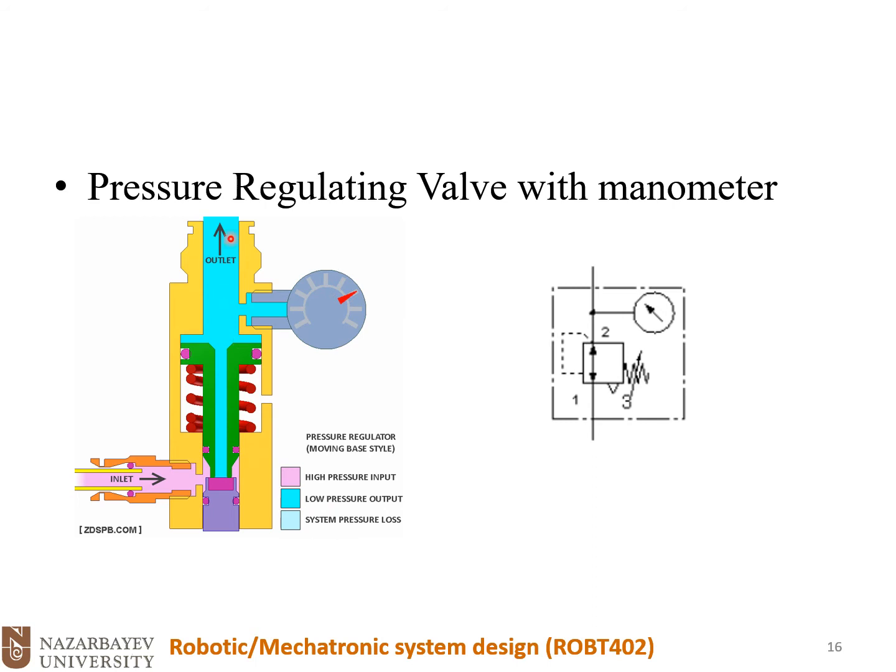So you see that this drop is reducing the air pressure, because mainly they are designed to reduce the pressure at the input and cap it at the desired one. And if we have a system pressure loss, or the pressure increases too much, then basically this piston will be pushed back completely and the air could be exhausted from this port here, and this is port 3.